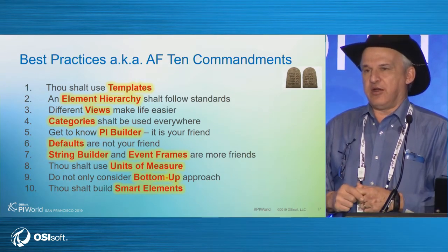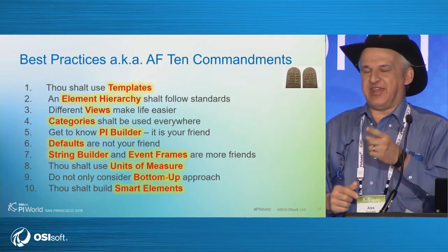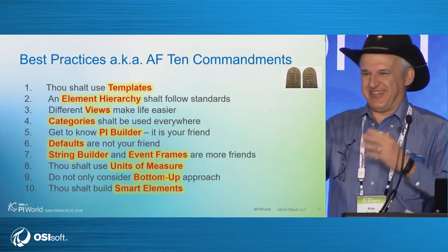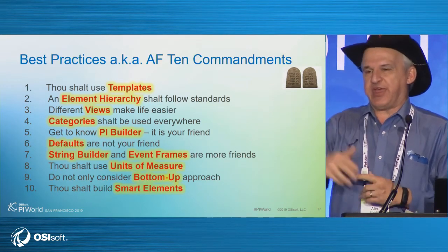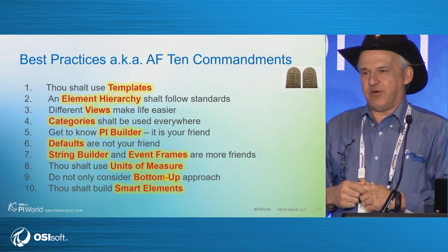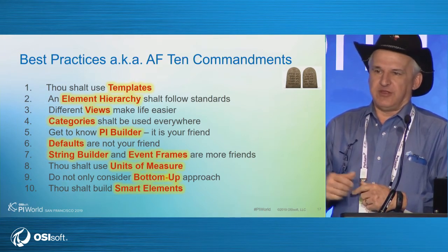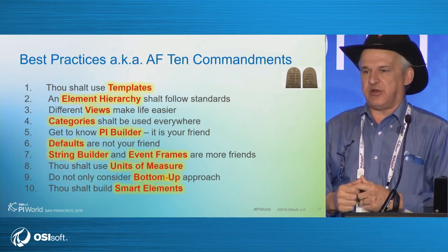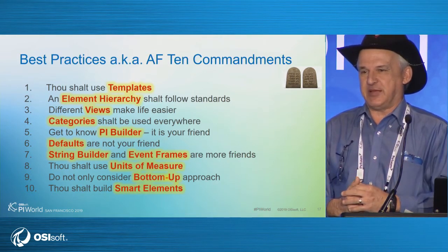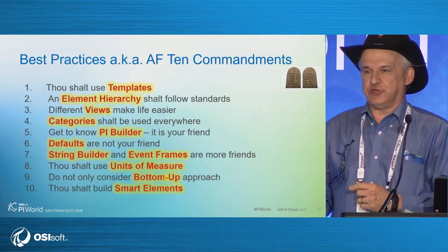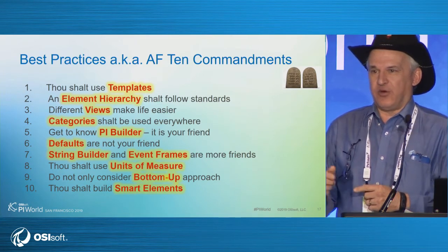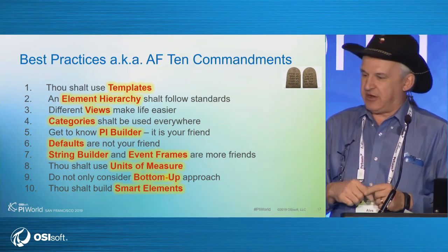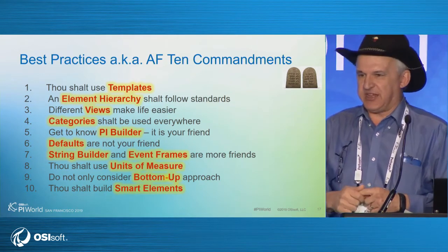Now, later on, I deploy it and say, you know, I didn't want kilograms. They were screwed up. It should be 1,000 kilograms because the numbers are big. So my attribute should be showing 1,000 kilograms. Well, guess what happens now? Because it was default, it says, oh, the PI tag's in 1,000 kilograms. Now you get a value that's actually 1,000 off, right? 1,000 times smaller because it doesn't do the conversion. So set a PI tag, have your unit of measure, click the default and explicitly say,